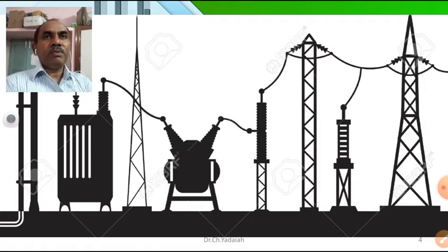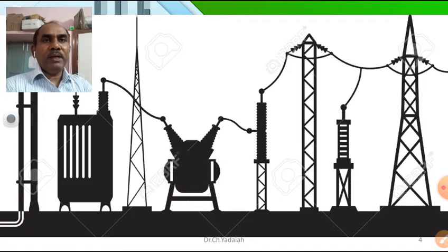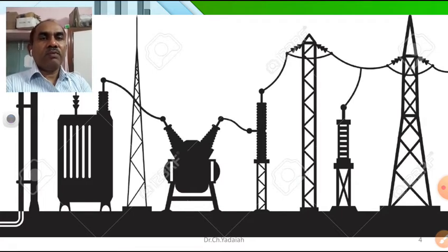Then there is a possibility of abnormal changes in our electrical energy, due to high voltage, high currents, short circuits, and insulation of the systems may fail and collapse the total system. Hence we have to ensure all equipment is perfectly controlled, perfectly insulated, perfectly isolated, and at the same time all non-current carrying metals should be at earth potential.